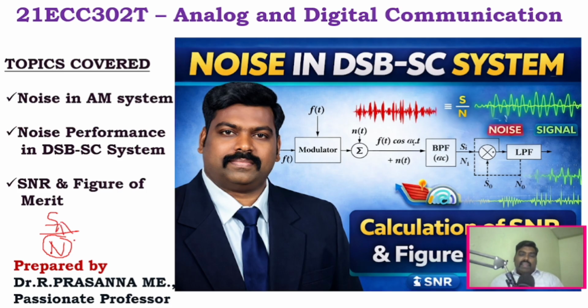So if the SNR is high, it means the signal power is good and the noise is very less. If the noise becomes high, then the SNR will become very low, which means it will degrade the performance of the system, right? So signal to noise ratio tells you how good the signal power is.